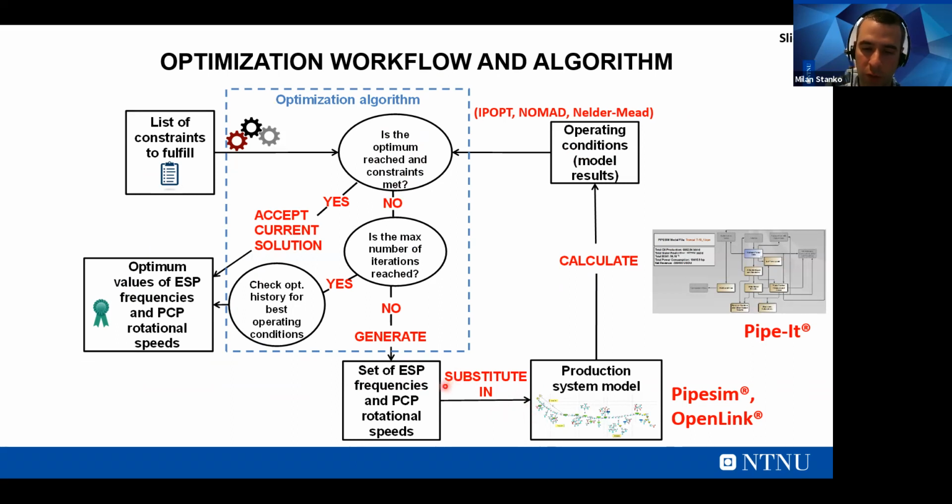The frequency is initially 60, then you do a small perturbation, for example 61, and then you find that partial derivative, and then you assemble your whole matrix of derivatives with all the frequencies. You do the same for all wells, and that's how you find your next point. You choose the direction in which you're going to get maximum oil. Maybe some frequencies have more effect than others.